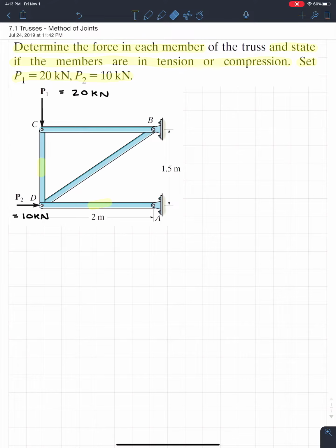So if this is the case, like I said, there's two methods. The first one we're going to cover, though, is method of joints. It's kind of the simpler method, mechanics-wise, where it's not very complex, but it could become very tedious when your structure is quite a big structure. One thing that you guys will see is if we had a very long truss, and I'm trying to find just one of the forces, let's say right in the middle of the truss, method of joints will become very, very tedious, and you won't want to do it. And that's when we go to the second method.